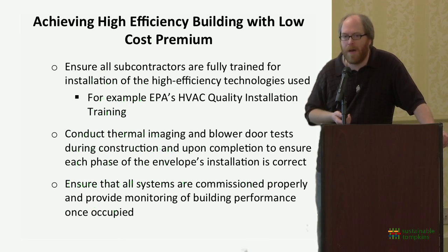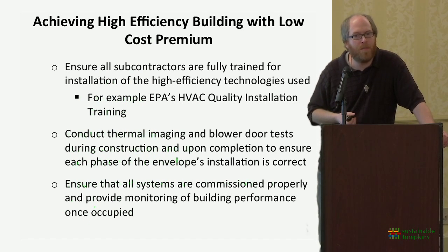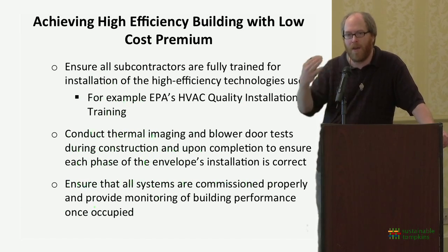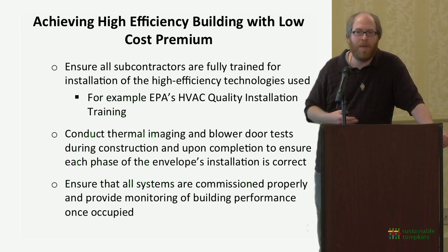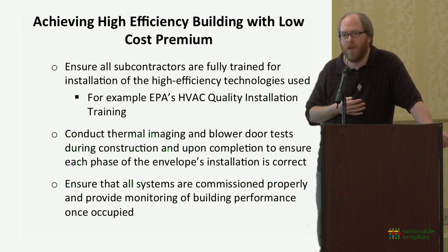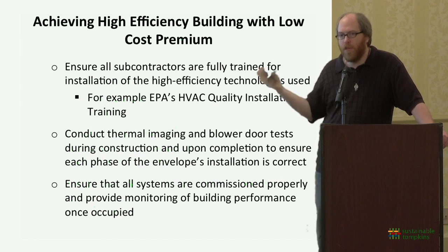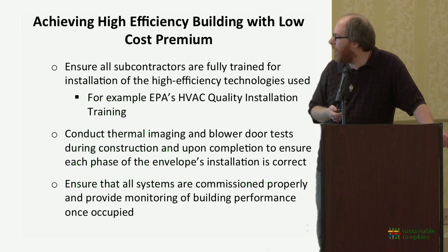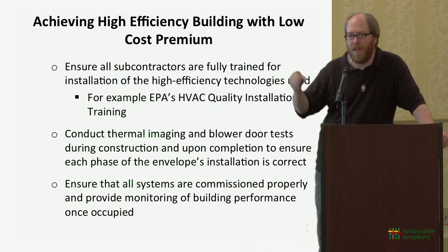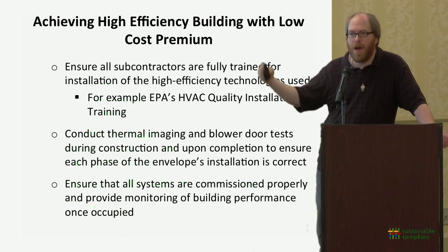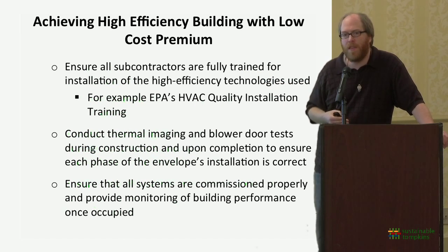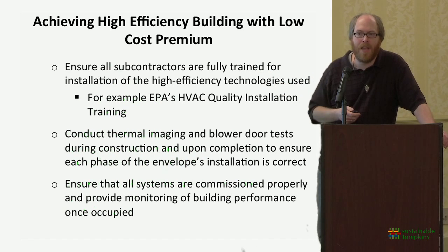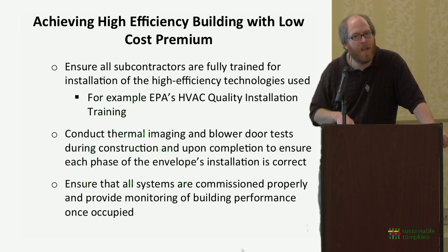And then to commission and monitor the systems. High efficiency systems require them to be run properly. If people bypass all of your control systems because it's easier, you're going to lose all of that efficiency in the end. So you want to be able to monitor these post-system. This company monitors monthly for the first bit of time. It monitors quarterly for up to 2 years, and then out to 5 years it monitors annually to make sure that the buildings that they designed are actually performing as they should.